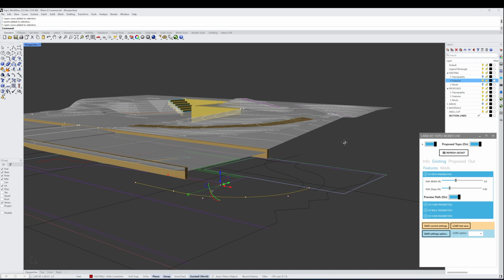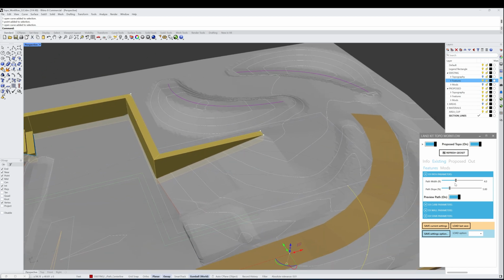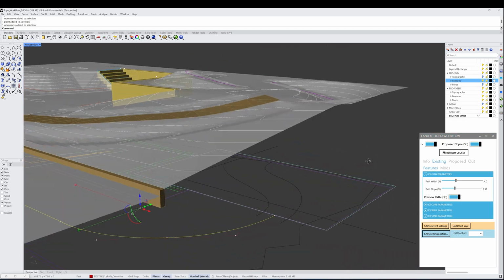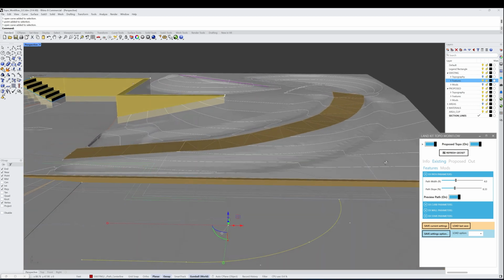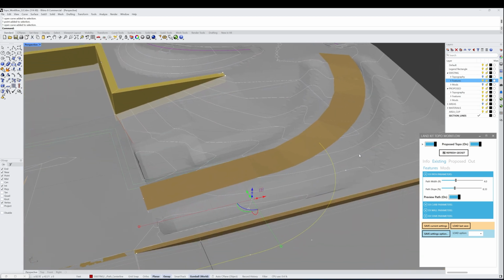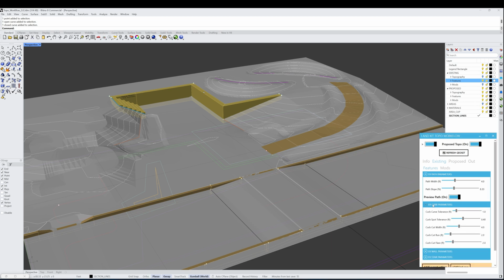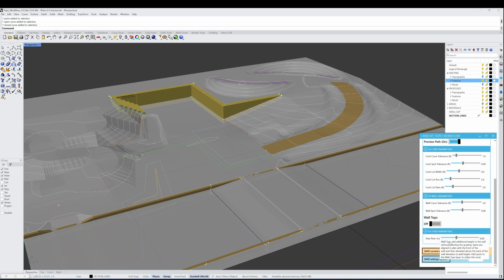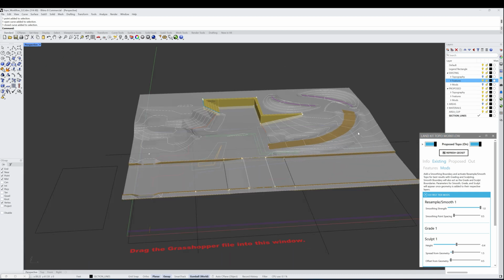So I don't really like where this path is falling at this elevation. What I'm going to do is increase the path slope to 8.33 and create a path that generates a flatter landing here at the top. And you can see now the path hits at a flatter landing at the top where these mounds are being represented. So the ability to adjust these things is done using the different parameters in here. And you can see we have different parameters for each of the different types of geometry and features that we're working with in this. Same thing with the mounds here that we have.